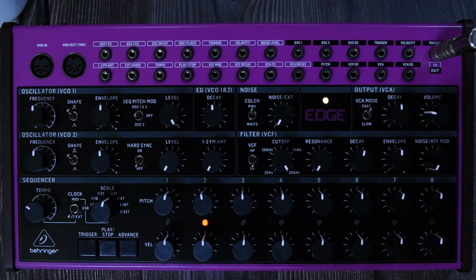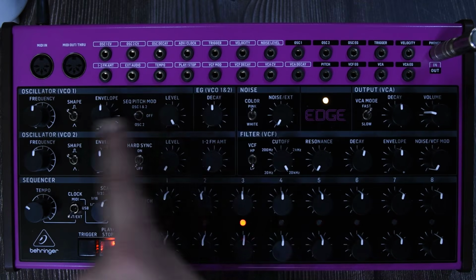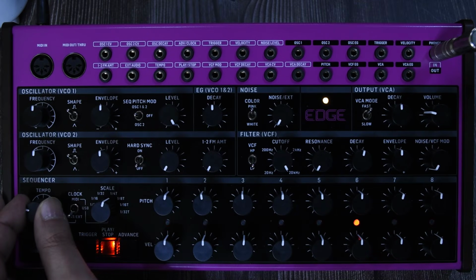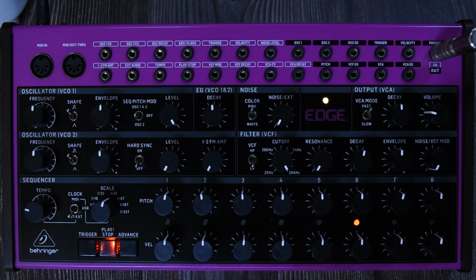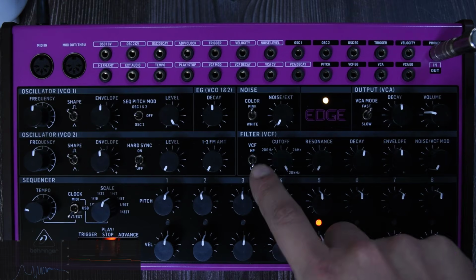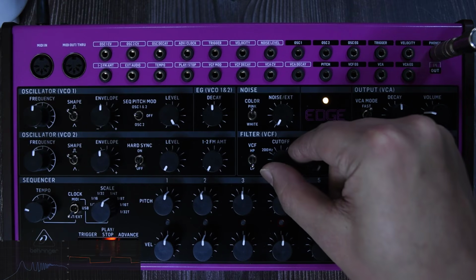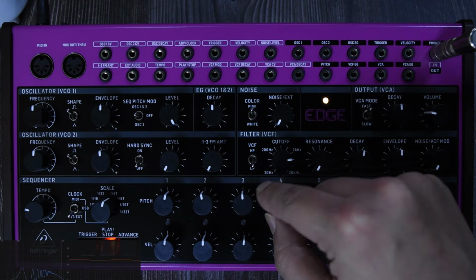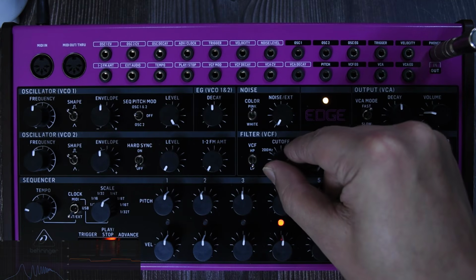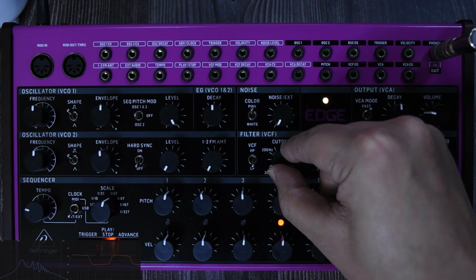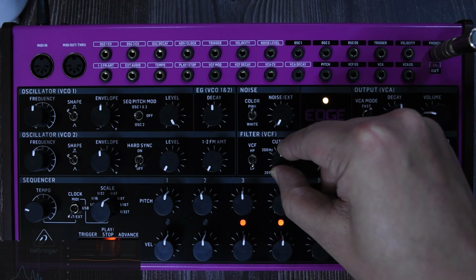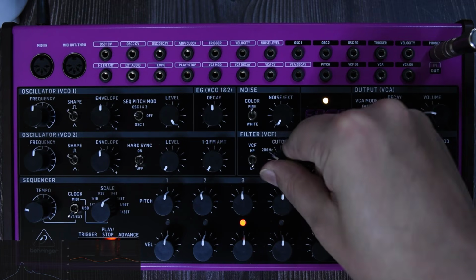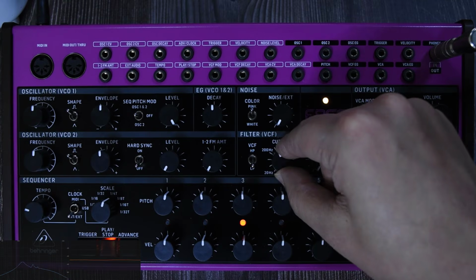It's a very simple filter. If I play it and I'm using just the oscillator number 1, I'm going to go a little bit slower. We're just using the oscillator number 1. You can choose between a low pass and a high pass. It means if I go to the cutoff and I start moving it when we're standing on LP, we are chopping the higher frequencies. We can see it right there in the spectrum. Right, if you go all the way down, you're just cutting pretty much everything.